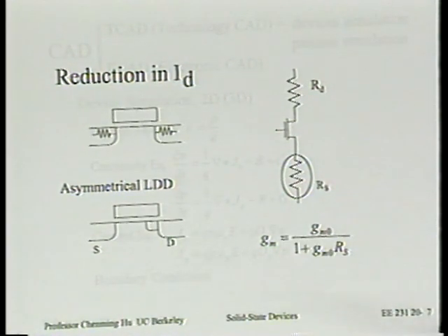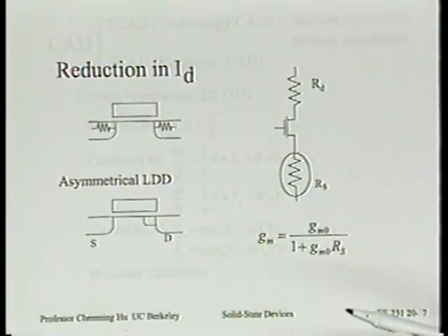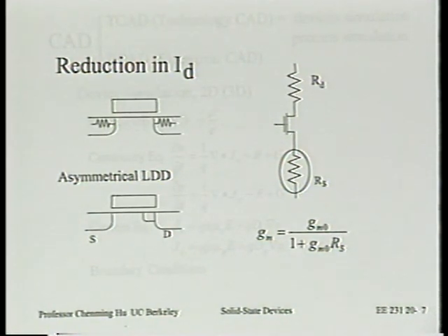So if you are now ready to do some more theoretical consideration of what can potentially be accomplished, we can certainly use the information we have for the minimum LDD length, right? And the second part, which we haven't done, is, as I said, you could do it as a homework, to actually find out what kind of profile will minimize that length, and therefore what kind of doping density is involved, and therefore what sheet resistance, and therefore what RS. In fact, we can even change that homework to what doping profile will minimize RS rather than minimize the length of the LDD.